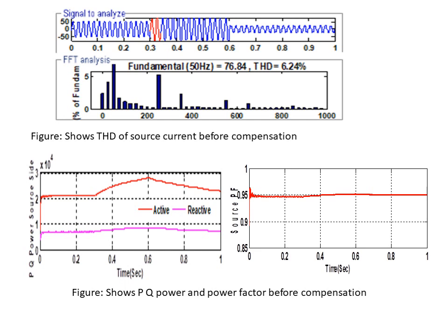The power factor of the system without compensation, which is shown over here, is roundabout 0.95, which is less than unity, that is 0.95 lagging. So it is essential to increase the power factor approximately to unity. And before compensation, the active and reactive power present in the system are 22.26 kilowatt of active power and 7.01 kVAr of reactive power.